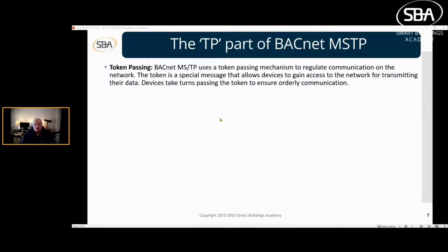I know that Modbus recently released a statement saying they will no longer use the master slave language, that they're going to client server. LAN has gone to client server too. I do know that BACnet is looking into it, but they haven't made an announcement about it yet, but an announcement should be coming. In the meantime, master slave only means that you have a device that's in charge, and all the devices that are connected to that device listen to that device and take orders from that device and do what that device says, and answer the device when it asks a question.